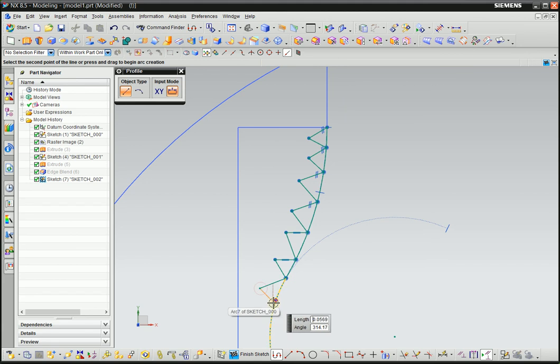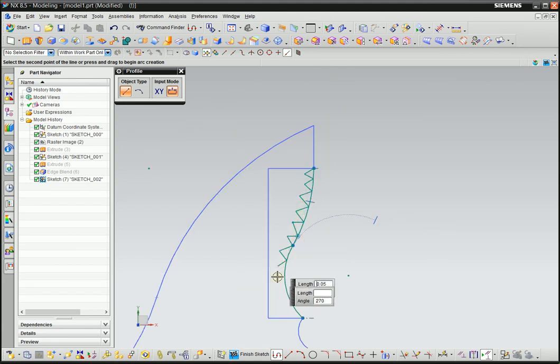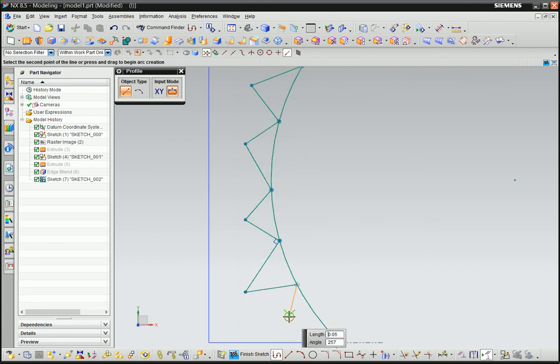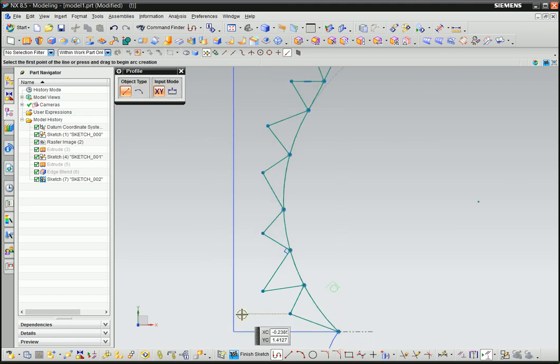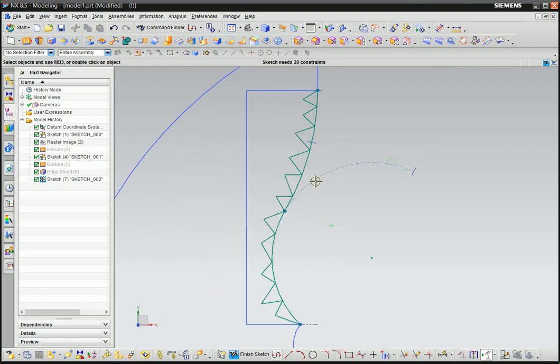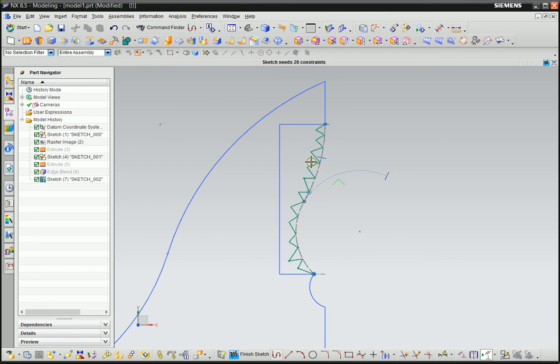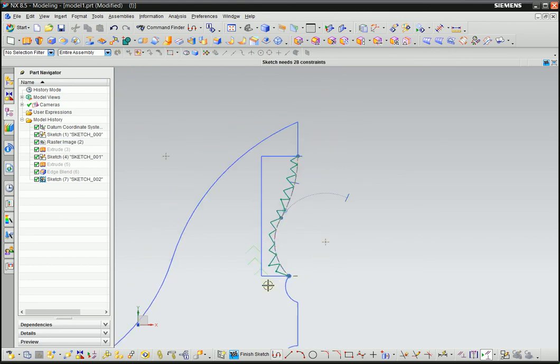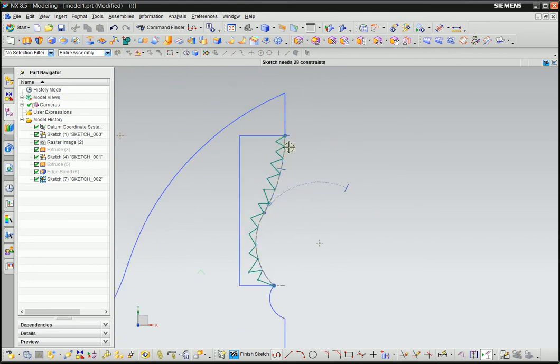Okay, as you know, the shape is not required to the bottom, I'm gonna be careful a little bit. Okay, and now we can keep this arc. Just turn that into reference, so this way you know where your teeth land. And still we have in this sketch, if I hide this, we only have the teeth.